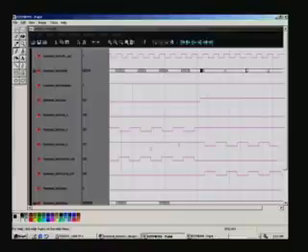So, now also notice that this OE bar is the read signal here, OE bar has started becoming active here, and write has stopped. So, the safe state is the high state, that is the inactive state for the write, both being active low by design, and that is why it is like that. And you can clearly see that the write pulse stops here, with the switchover of RWN, and reads start here, and once again you can see that the write counter has been running in support of the write pulse. Now this also has stopped here, and instead the read counter is activated here, which aids in generating the OE bar signal here.